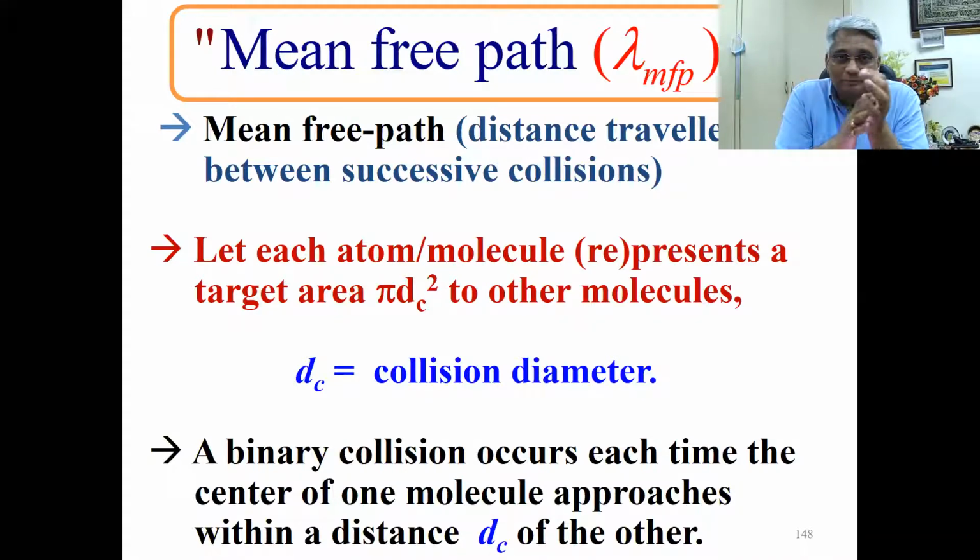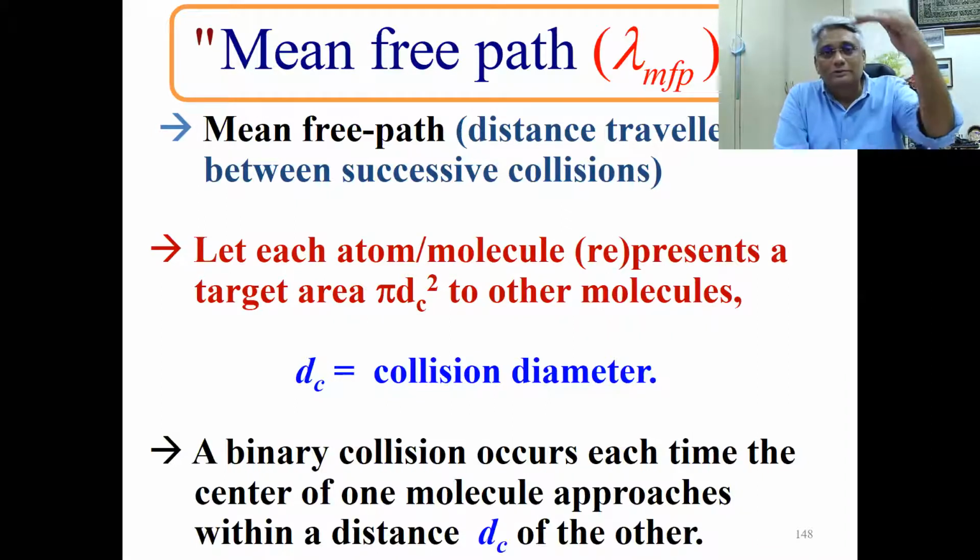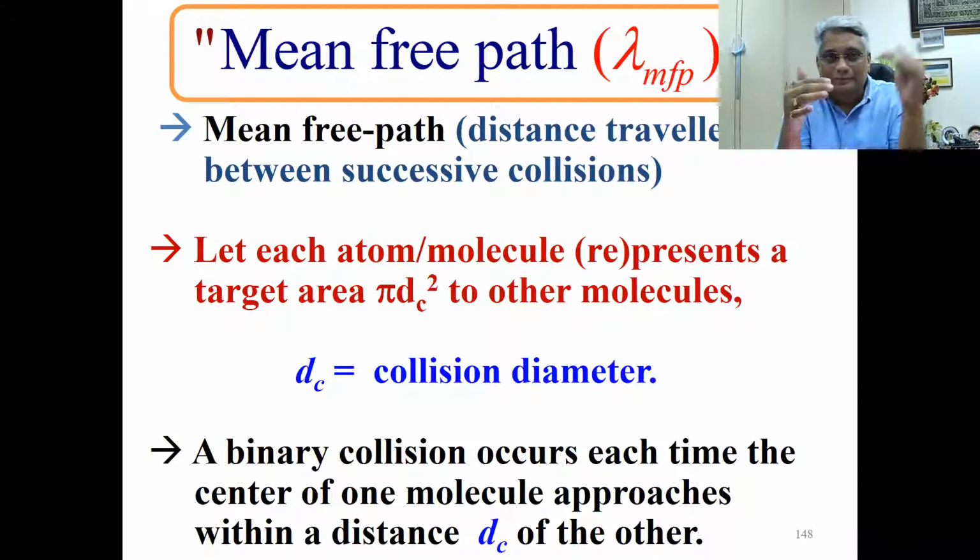But then you may sometimes have to do a reactive way of thin film deposition. It means you start with a charge of titanium and you melt it. You create a plume of titanium atoms, and if these titanium atoms deposit on the substrate, you have a titanium thin film. But I can also make a compound by introducing nitrogen gas inside the chamber. That means I get titanium to get nitridized, so I get a titanium nitride film on the substrate. If it is only titanium deposition, I can do it in high vacuum, 10⁻⁶ or 10⁻⁷ torr, so that there are no air molecules present inside the chamber to oxidize titanium.